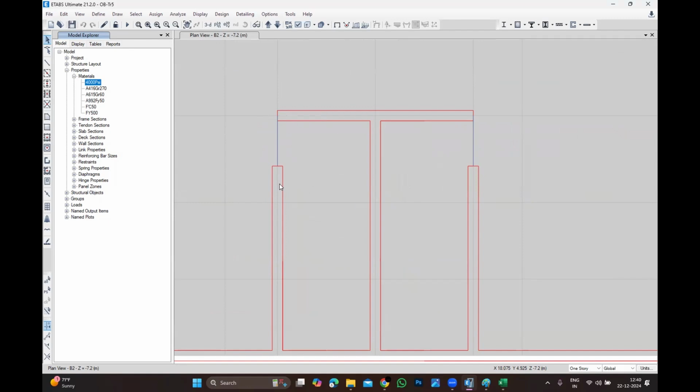Both are the same. Okay. Usually for a spandrel beam, we used to go with this or this, as an easy way of modeling. If it passes, it is okay. If it does not, then I'll go for modeling the wall with the opening. Then it is going to be treated as a wall. No. I will change those portions to a spandrel beam.